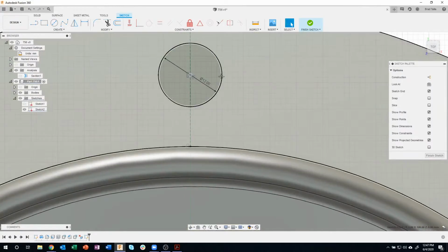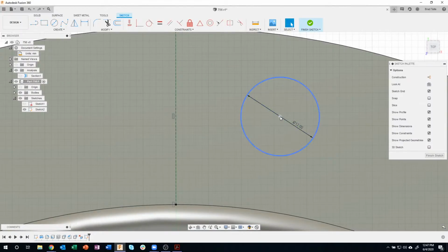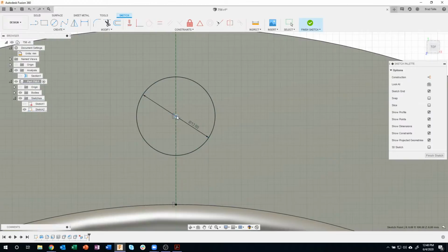Let me maybe try that again. I'll do it closer. I'm going to grab this guy. It's going to get near the line, so I know it's coincident. But watch what happens here. I can't really point to it, but there's a little blue triangle about 11 o'clock from my mouse. Okay, so that's a visual confirmation that it's snapping to the midpoint.